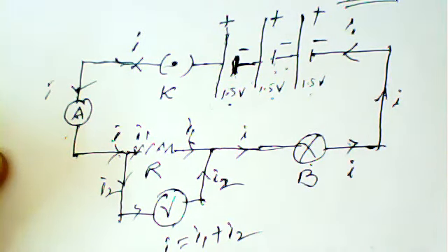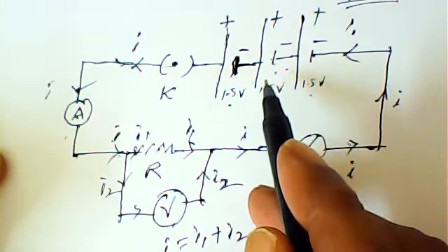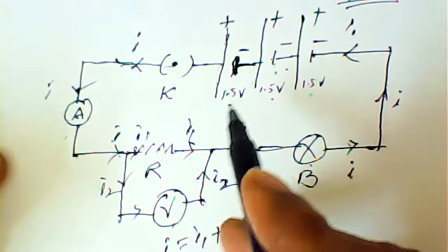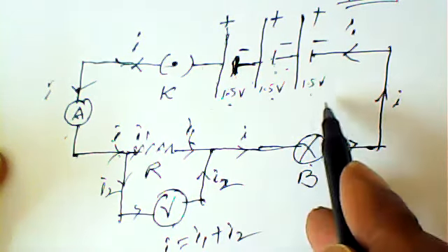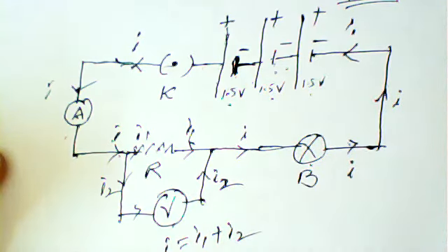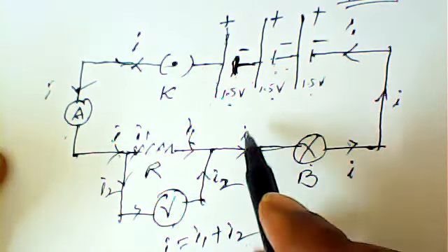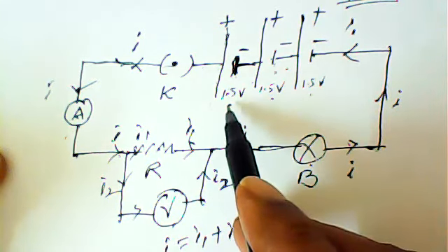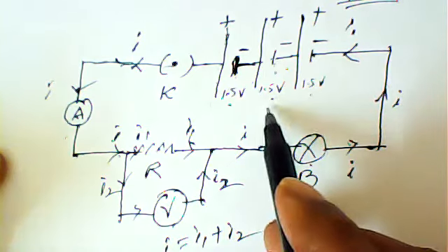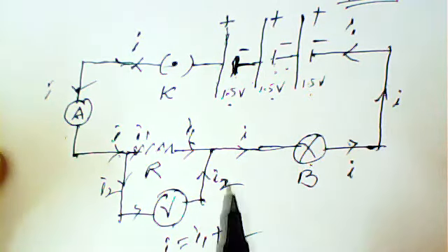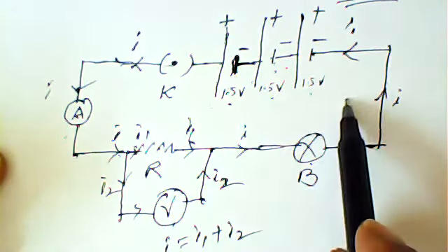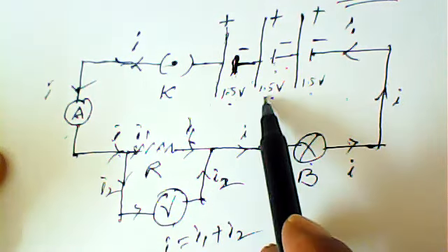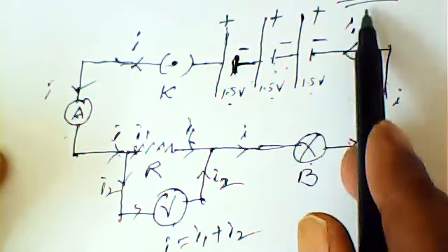across this circuit. If instead of connecting this series connection, the cells are connected in parallel, however many cells you connect, 10 or 20 of 1.5 volts, you will get only 1.5 volt in parallel. Suppose you are connecting a 1.5 volt cell and a 10 volt cell, whichever is highest in parallel, that only will be the voltage. So in series we have to add these: 1.5, 1.5, 3 plus 1.5, 4.5 volts.